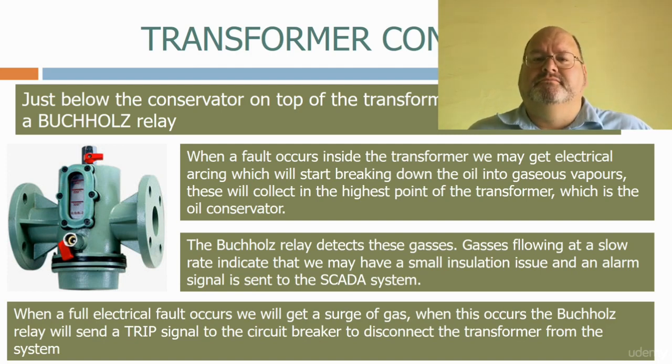If you want to test the Buchholz relay, the best way is to use a foot pump to simulate the gas flow. Pumping slowly should set off the alarm contacts. Pumping quicker will set off the trip contacts.